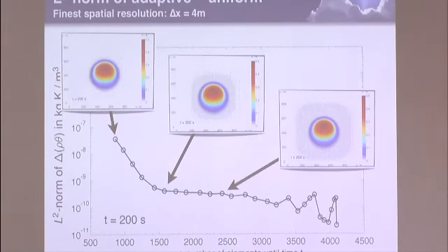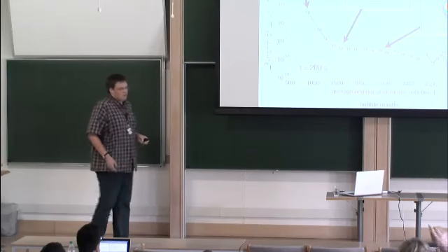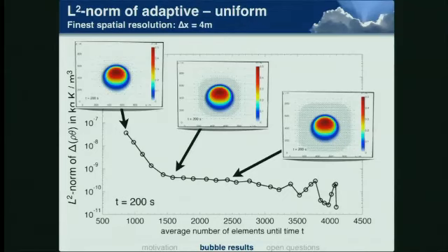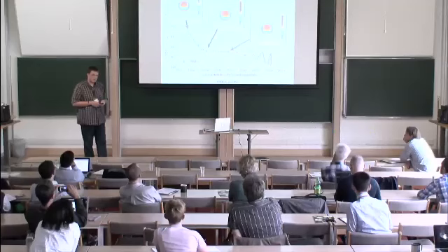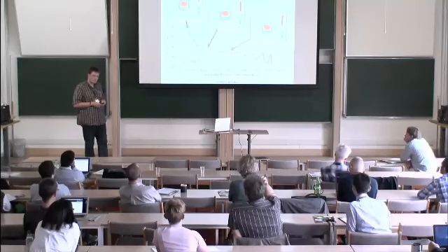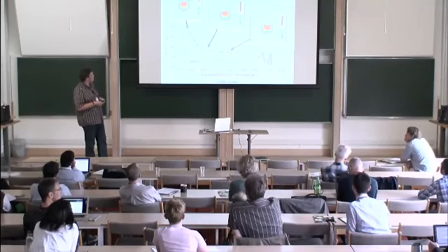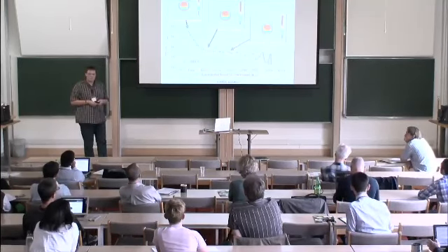At this fairly early stage, you can still distinguish between simulations that were affected by adaptivity and other simulations that are almost not affected. If you would take the uniform simulation and then also compute that on the next finer mesh and compute this L2 norm difference, in what range would that error be? Would it be this 10 to the minus 9? So are you hitting the level of discretization error there, or are you already below that?